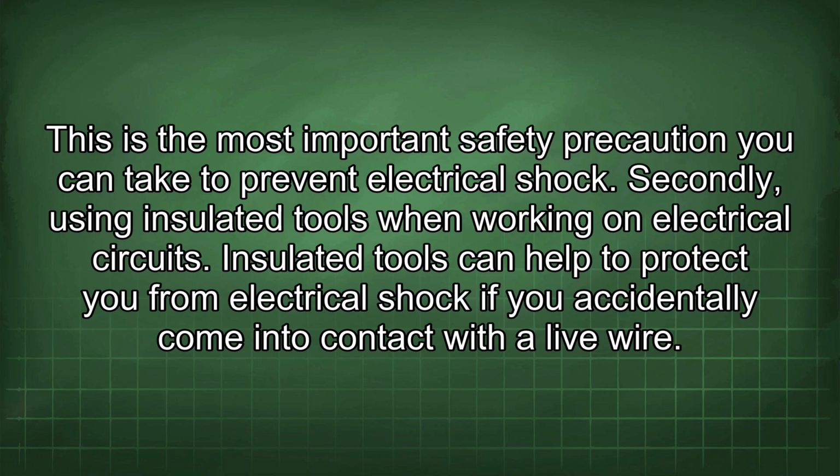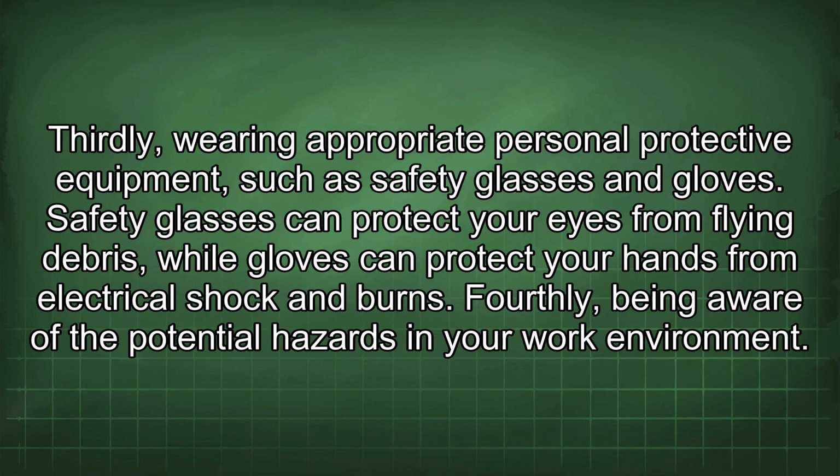Secondly, using insulated tools when working on electrical circuits. Insulated tools can help to protect you from electrical shock if you accidentally come into contact with a live wire. Thirdly, wearing appropriate personal protective equipment, such as safety glasses and gloves. Safety glasses can protect your eyes from flying debris, while gloves can protect your hands from electrical shock and burns.